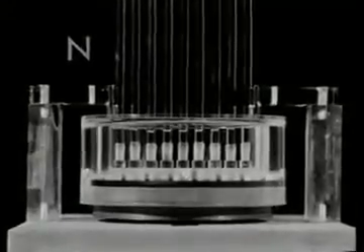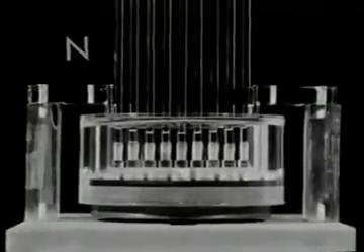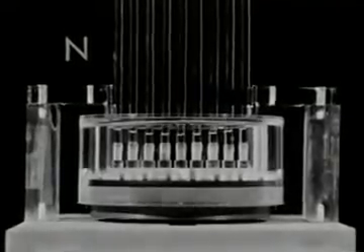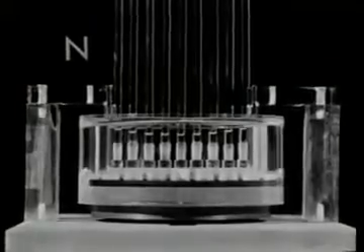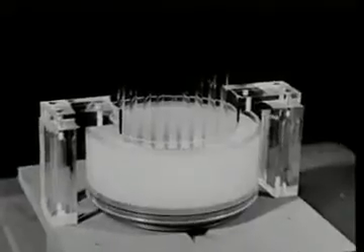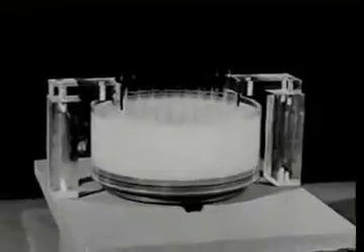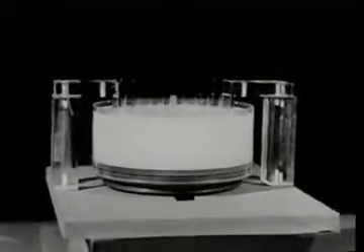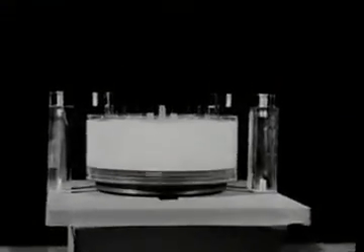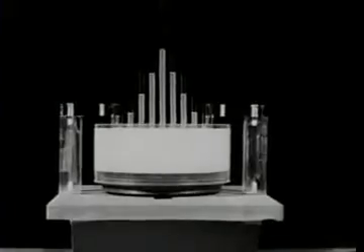If the fluid is Newtonian, the height of the fluid in the tubes at steady state is a little less near the center than toward the outside. For a non-Newtonian fluid at the same speed, the force normal to the stationary plate may be considerably greater toward the center. Although the steady-state stress distribution between the plates is attained almost immediately, again it took several hours for the levels in the tubes to reach their final positions.